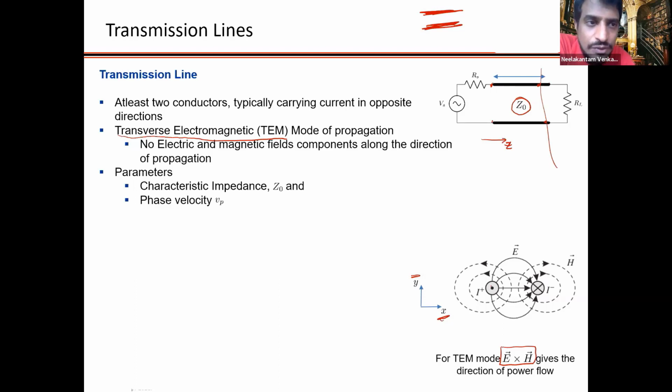So from here to here is not a short circuit. It's a wire that is long enough. So that's why it's pretty thick, and you write it with Z0. It has a certain physical length, maybe L. You connect it to the load resistance RL. The source here has a source resistance RS. So that's how you figuratively represent a transmission line.